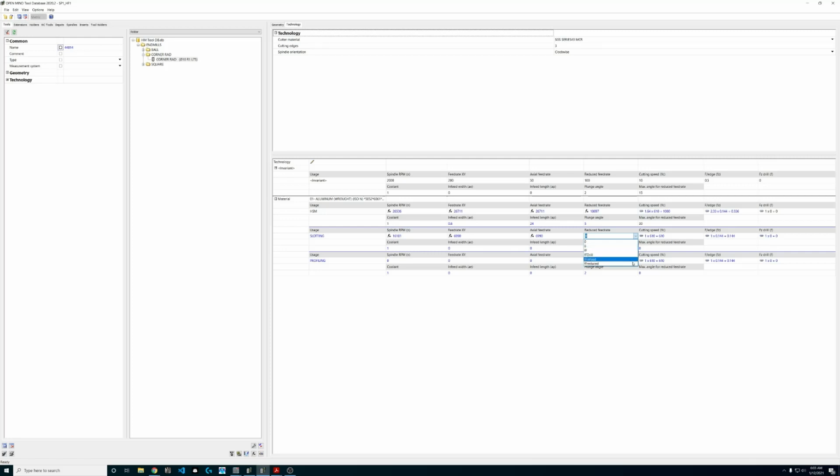Unfortunately, by default, at least to the best of my knowledge, we kind of end up with empty formulas again once we have to modify the parameters past a certain point. Or obviously, we might change if we have a major change in cutting diameter. Some of these values might change. While hyperMILL is automatically going to change our surface footage and feed rate based on diameter because we defined it in our material setup, things like the infeed width and infeed length, it's agnostic to. It doesn't know anything about that.